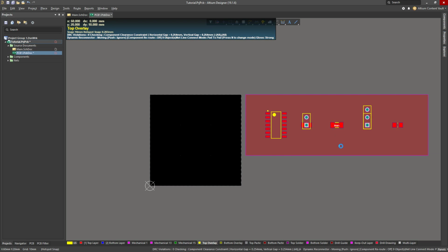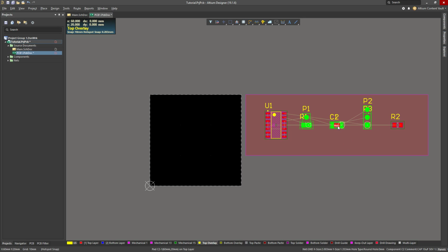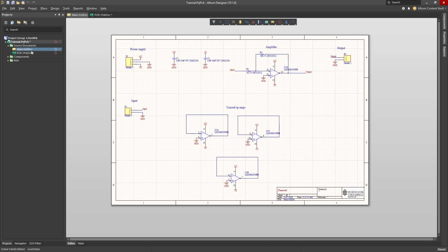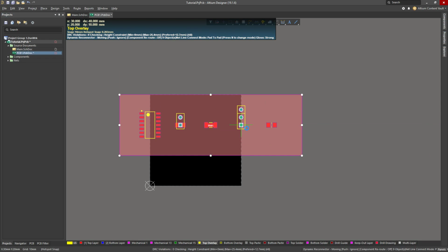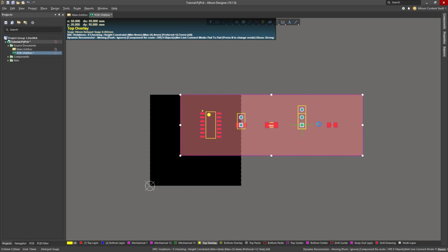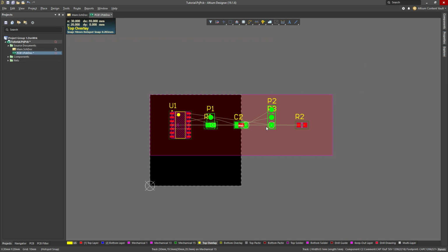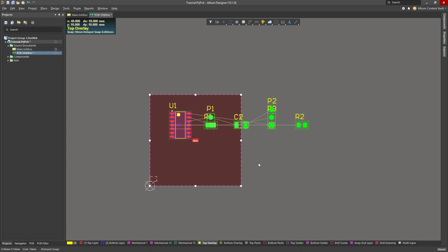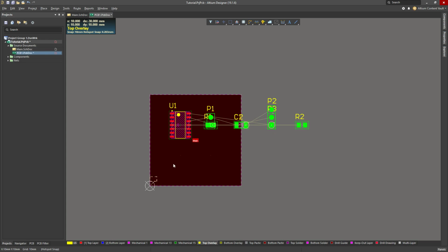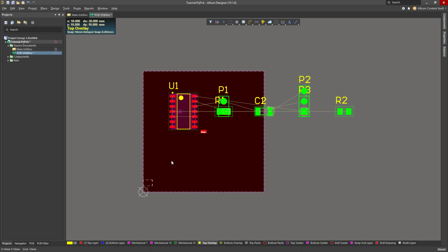They have been placed into this red box here with the label main. That comes from the name of the file of my schematic. This object here is called a room. The intent with this is that we can define certain regions of our printed circuit board that will relate to certain aspects of our circuit. If you have a complex design, you might have multiple schematics, and so you might want to reserve portions of your board for certain parts of your project.